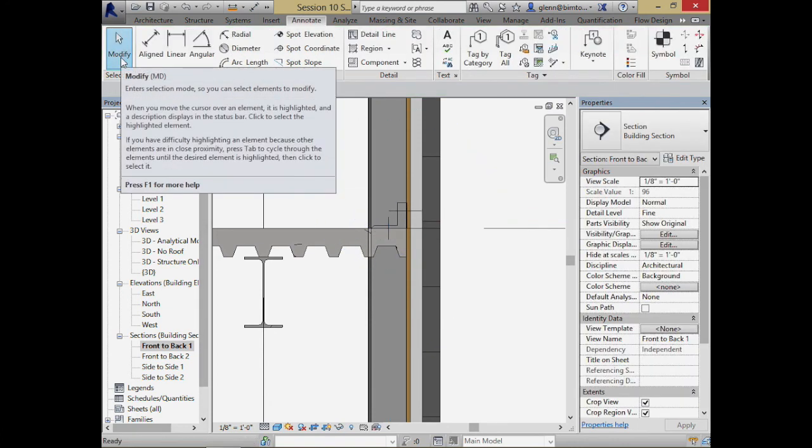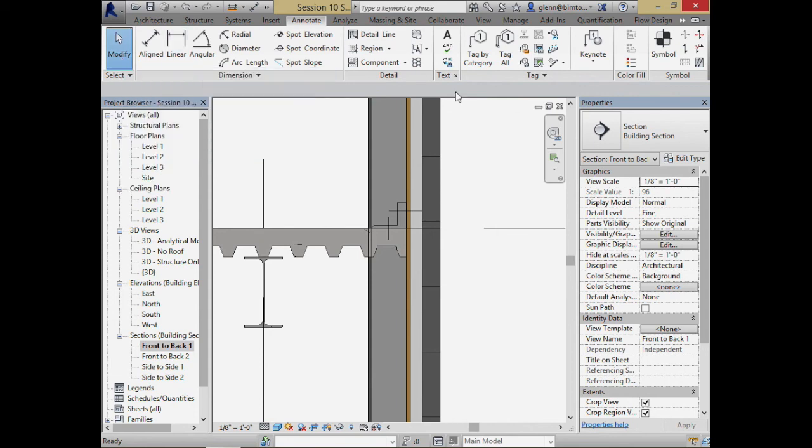And that's really where we get the whole notion of a curtain wall. It really just is a panelized system that hangs. So even though as you look at the Y2E2 building, or any of the buildings in the SEQ here, they look like they're all these stone panels, it's really this precast panel. It has very thin layers of limestone attached to the outside. But they're really just trucked in as panels and stacked up on the building, and some guy comes by and it is bolted into the frame of the building. And it's really just all carried by the floor. So there's really no load coming down to the walls, which is kind of interesting.